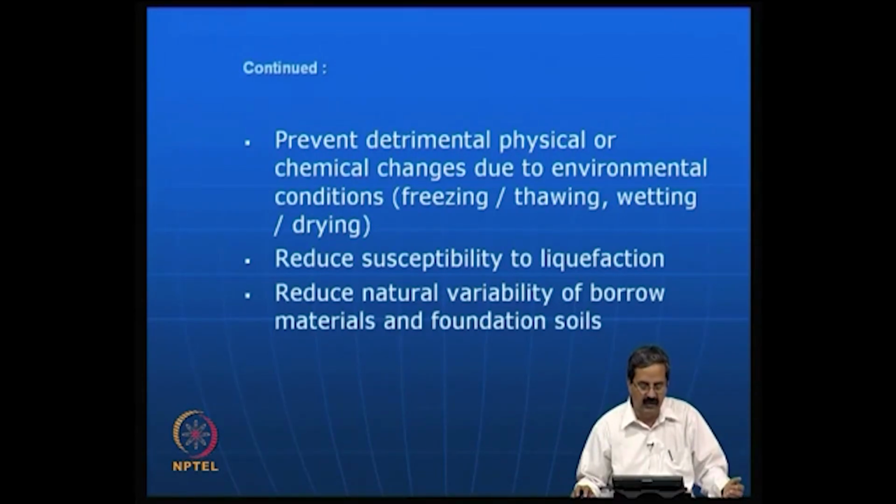Then one of the important aspects of ground improvement techniques is to reduce susceptibility to liquefaction. You do not want all the soils to get liquefied when an earthquake comes. For example, the Bhuj earthquake created so many problems. Many dams collapsed because of liquefaction.